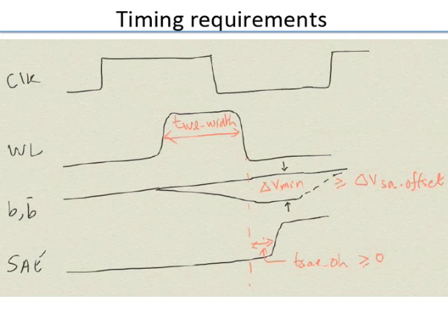Now the thing is that whatever solutions you have should be simple enough to get the job done, but not so simple that it really doesn't do it well. On the one hand, for example, you can say, look, I can have some precision control delay line, where I'll know exactly in picoseconds, absolute time units. Maybe I'll put that in and then generate these edges. But then the complexity and area overhead becomes very large. So you need to have a way by which you can get the solution to your problem.